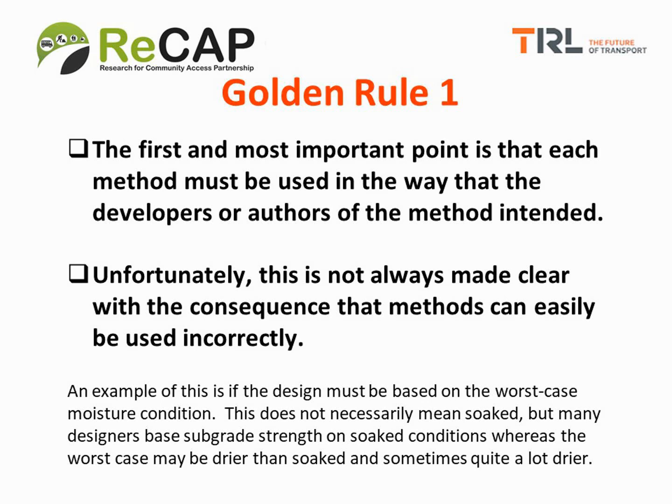A method may ask you to base your design on the worst case moisture condition of the subgrade. This does not necessarily mean soaked, but many designers base subgrade strength on soaked conditions, whereas the worst case may be rather drier than soaked, and sometimes quite a lot drier. So if you base it on soaked when you shouldn't, you'll be over designing. That's perhaps one of the most common errors, which we will come across later and show how to avoid.